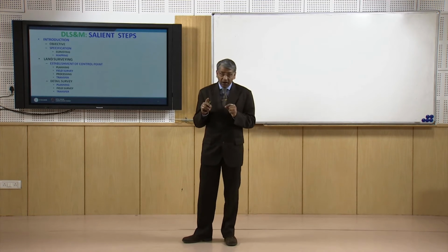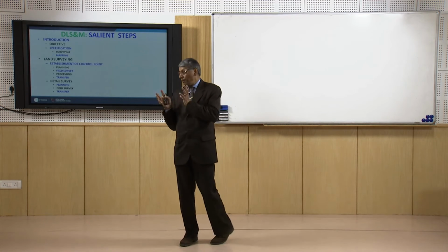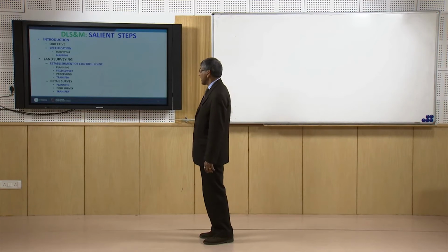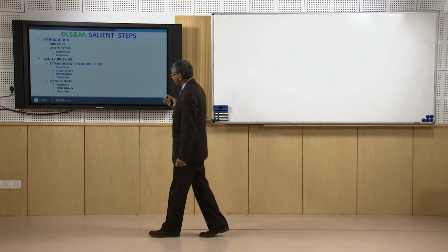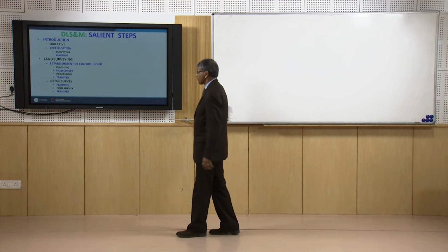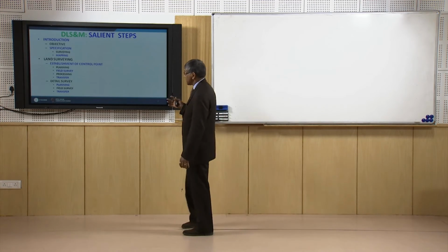data to the receiver, that is called initialization, like the cutoff angle, then the epoch of observation, then in which coordinate system we will be taking the data, etc. So, there are so many other things to be given. Once this has been set up, then as per our pre-plan we have to take the data, go on observing the data. Now, while doing the data observation we should go for intermittent quality checking.